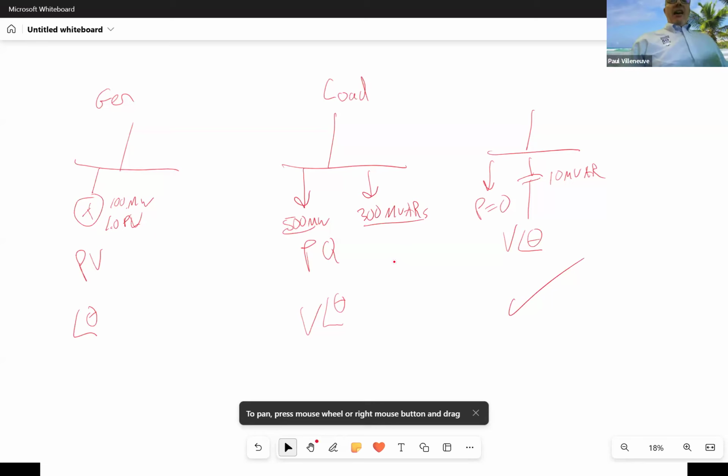And you should never have a load bus that also specifies V at an angle of theta. The reason is that you've scheduled 500 megawatts and 300 megavars, but the power is coming in from the rest of the system. So to deliver that power, the voltages have to be adjusted up and down based on how the rest of the system is operating. I can't just willy-nilly say this is going to be 500 megawatts and 300 megavars at 1.0 at an angle of 15. You can't do that because there's no way you could design the system so precisely to get that.